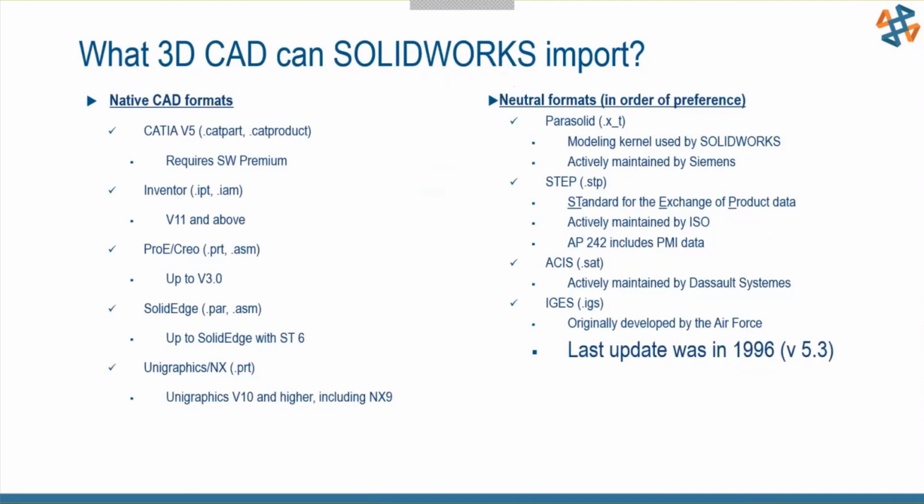There's limitations. And so they decided, hey, we're going to create this thing called the step file. And so basically that group just abandoned what they were doing in the IGES format and started the step and have moved forward with the step. So it actually shocks me that even IGES works at all as well as it does. But we want to steer clear of IGES files if we can.